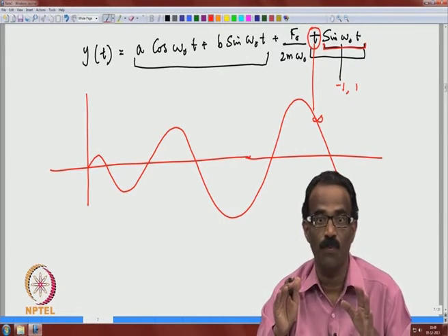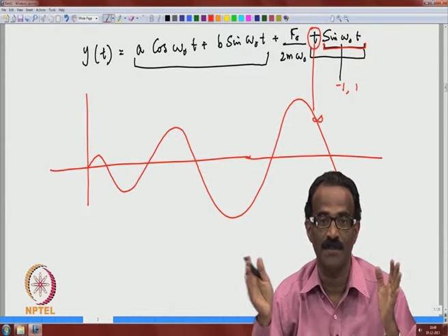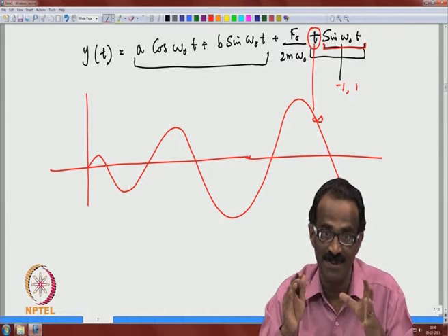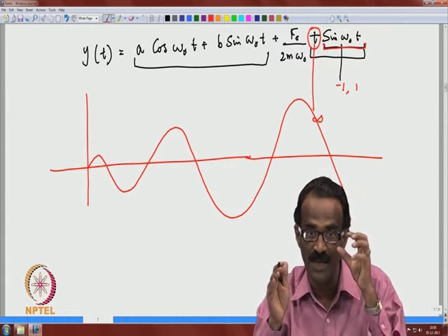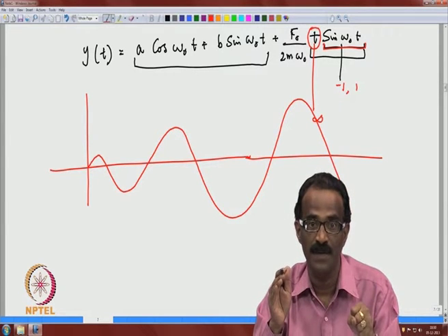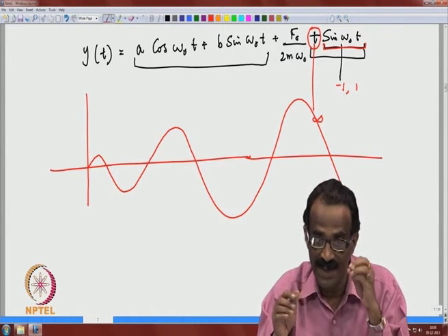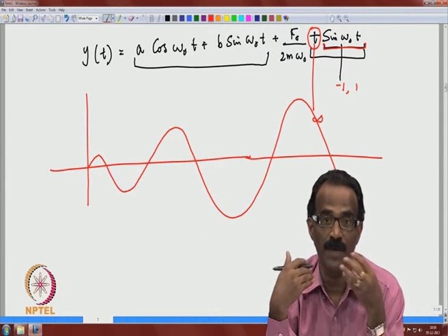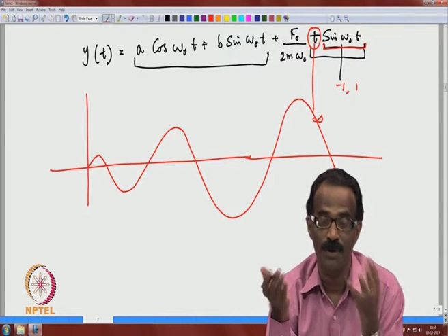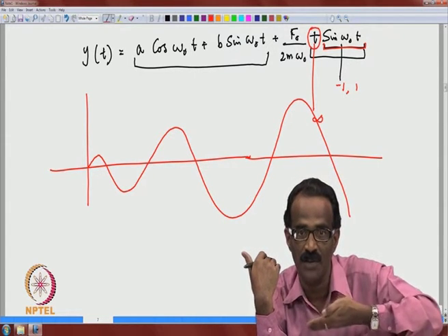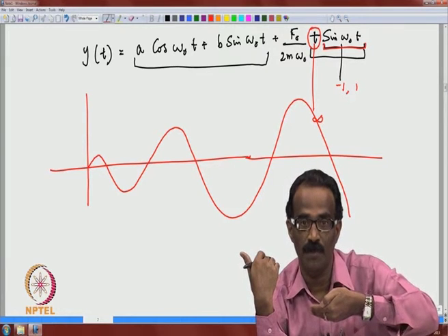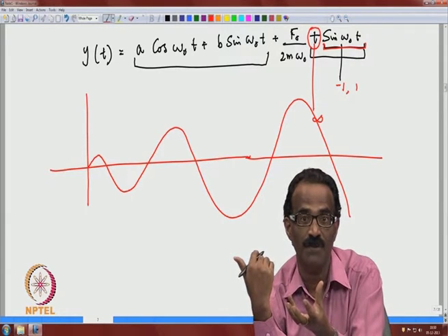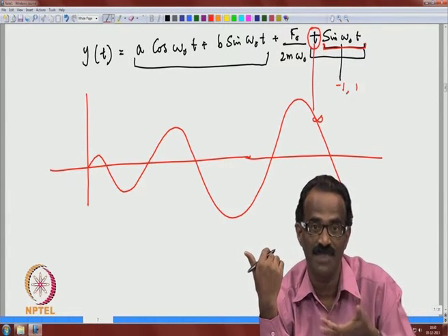And this is what you have to take into account when you design any mechanical system like a bridge or anything. You have to put enough damping in the system, because the external frequency may not be under your control. For example, there will be a lot of vehicles traveling through your bridge, and they will create automatically their own external frequency, and your system will have a certain frequency.